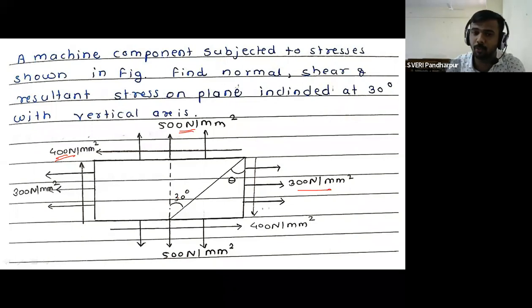Again, which rule do we follow here? We have to take the theta value which is between the inclined plane and the major principal plane or vertical plane. So first, while giving the problem, we were given the angle of the vertical axis, and using that we converted it to the major principal plane. So the magnitude will remain the same, and now your theta is present at this particular corner. According to that we have to take the sign conventions of theta also.